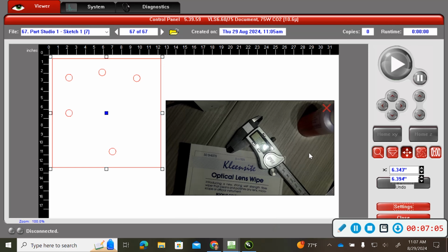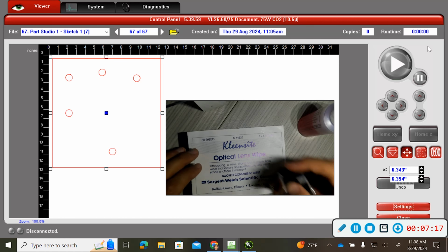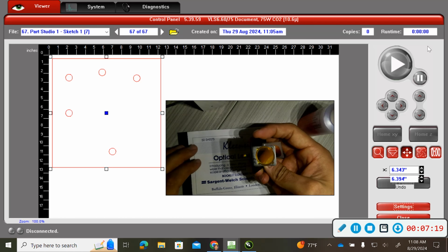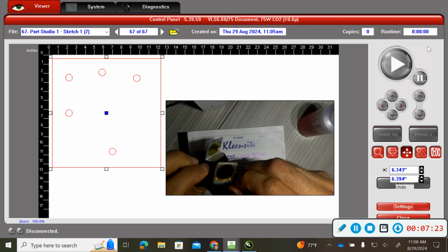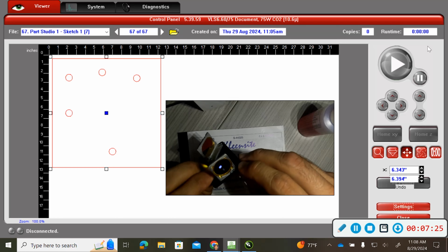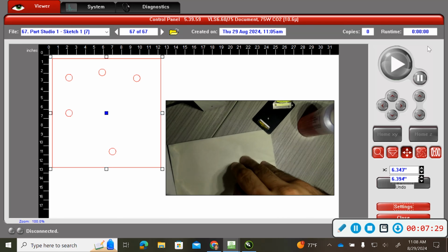So now in this situation, we are going to turn on our laser cutter by clicking a button that pops up here that's red. It's a power button. And before we actually run our laser, you're going to go ahead and take out the lens. Notice the lens looks like this. Please be very careful not to touch this lens here. If it looks cloudy at all, you do need to clean it. So what I recommend is you get one of these optical wipes. You're going to tear a sheet out.